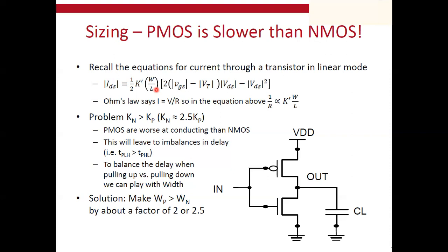You know that MOSFETs are unipolar devices, instead of bipolar transistors, where both electrons and holes contribute to the overall current. In MOSFETs, being unipolar devices means that you only have either electrons moving or holes moving. That's actually the difference between the N-channel MOSFET and the P-channel MOSFET. And here, when we go into the variation between electrons and holes, maybe we have to recall our solid state electronics basics, considering the mobility of electrons and the mobility of holes, typically in silicon technology, which is of course the most famous technology.